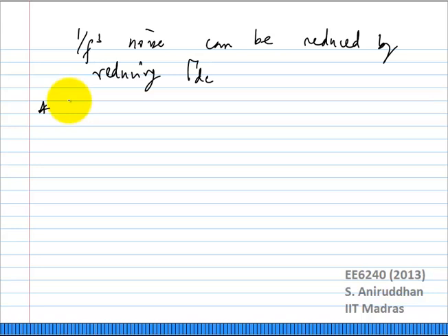So as it turns out, you don't get a flat noise region from the oscillator itself. But anytime you want to measure the oscillator, you'll have to put in a buffer, right? You can't load the oscillator directly. Similarly, the measurement equipment itself will have a broadband noise floor. Both of these things ensure that whenever you measure the oscillator, you will always see a flat noise region. But inherently, the oscillator itself does not have a flat noise region. The farther you go, the tank makes sure that the noise keeps reducing. And fundamentally we should expect that, right? You don't expect the noise to flatten out. You expect the tank to keep improving your noise performance. Okay?